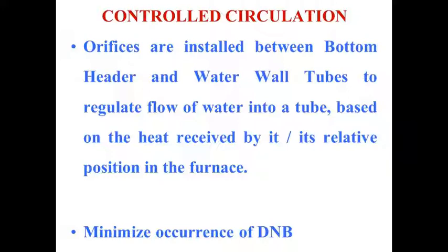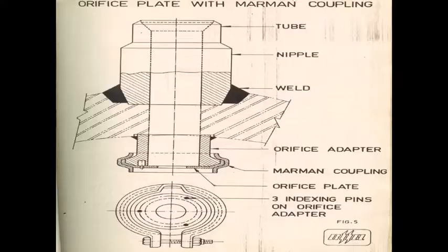Besides that, in the flow passage, we have to take care of heating in such a way that crossing the critical heat flux condition never arises, and this flow is entirely within the regime of nucleate boiling, and there is no chance of reaching DNB.